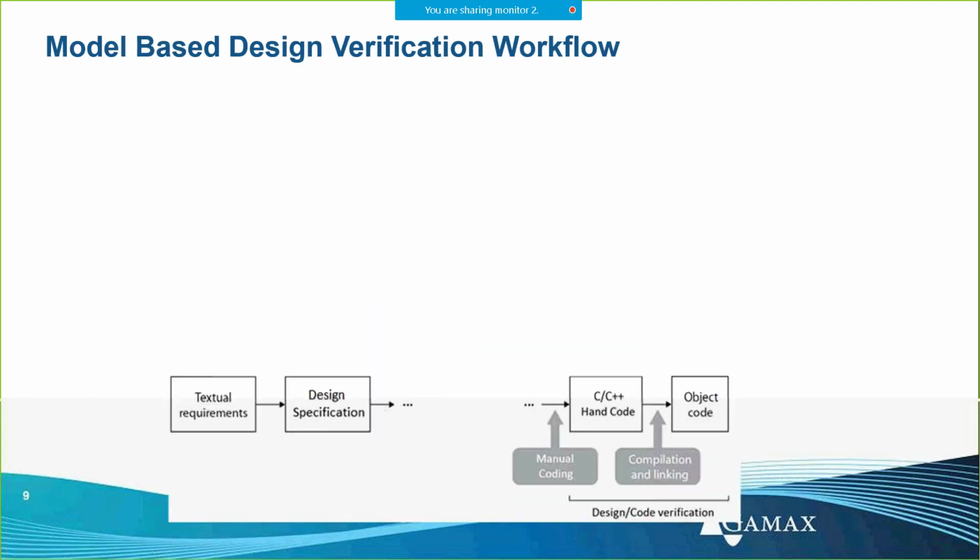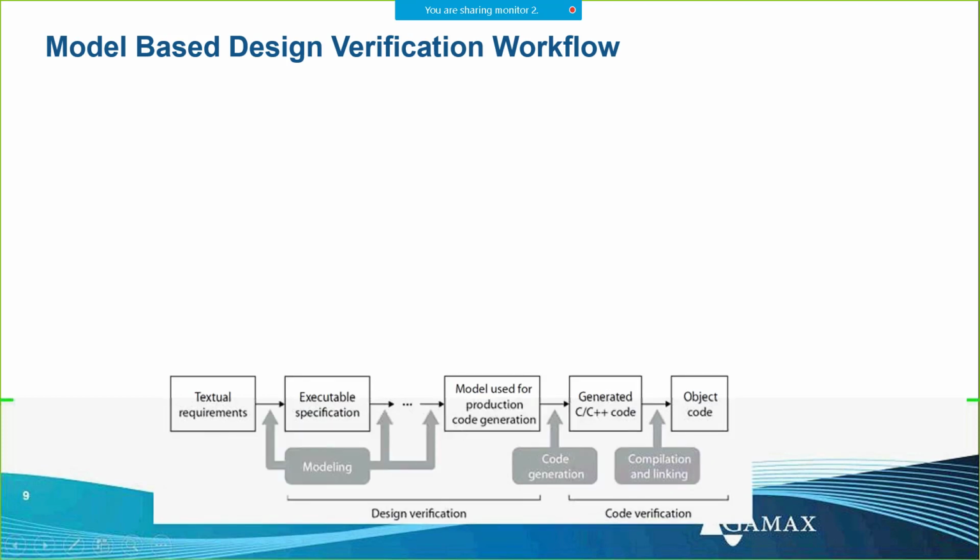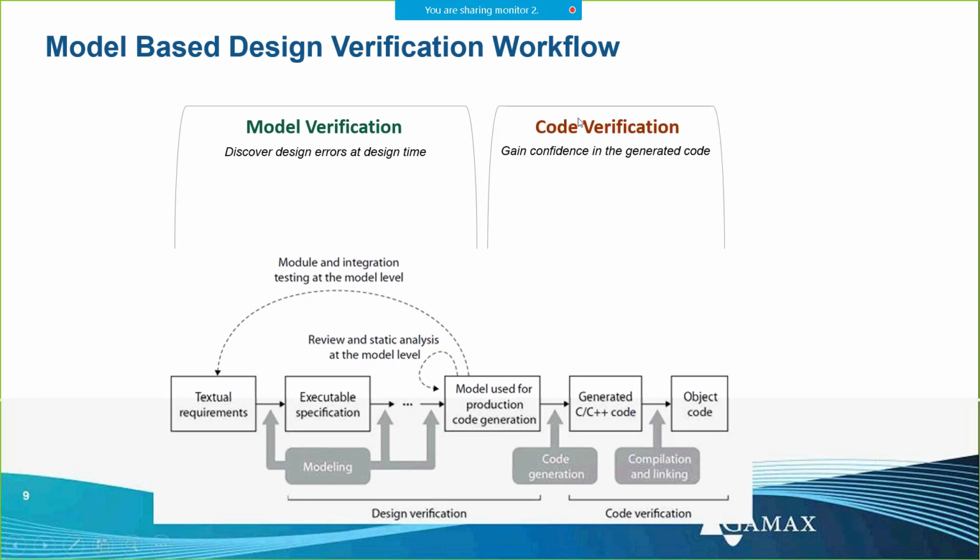So what does the design workflow look like? We start out from some requirements, then we do the design specification, and then we create our model, do code generation, and then we deploy. We have two parts: model verification and code verification.